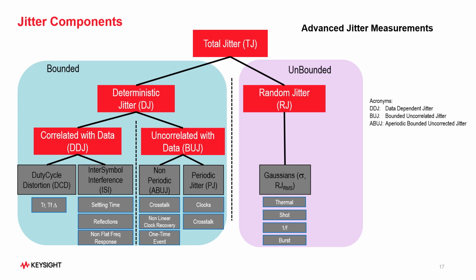But as we keep moving towards the right-hand side, that is highly unbounded, and these jitter characteristics are very different from what I described earlier. This jitter here is called the random jitter, or RJ, and it basically increases over time. Again, it's very important to know where the source of the jitter is coming from, so that one can identify the root cause of the jitter and help fix it in the design.